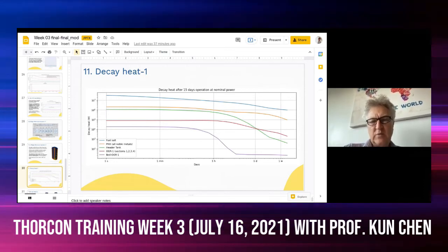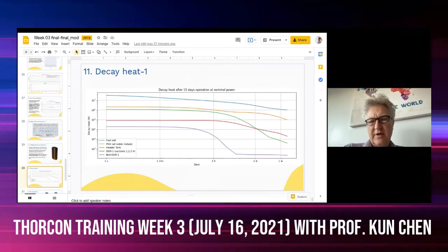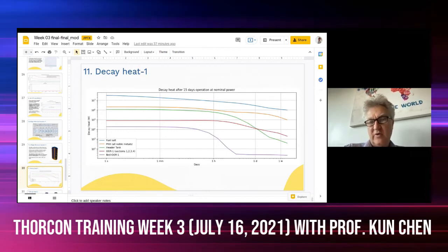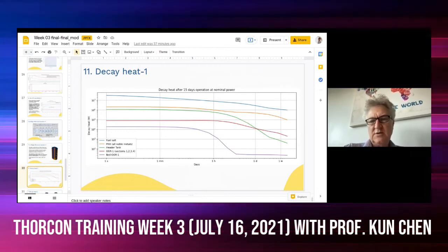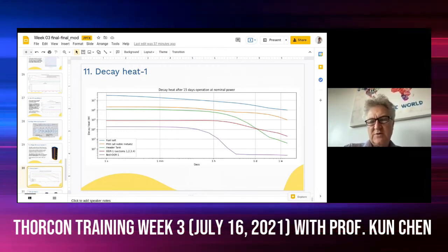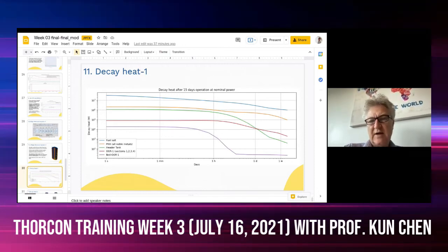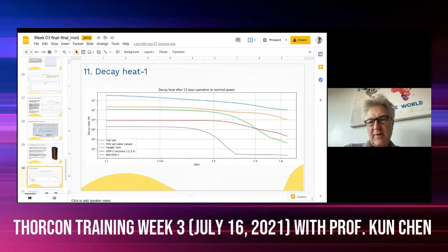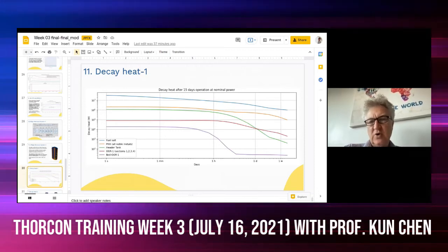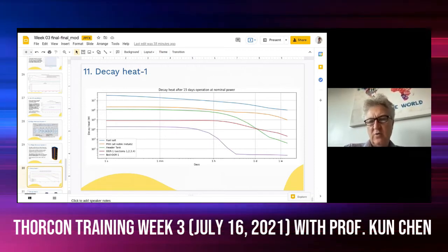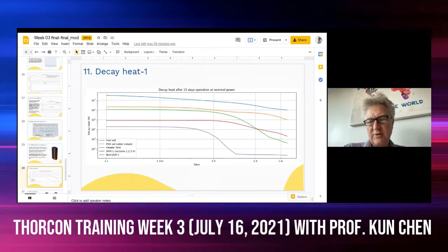However, as we pull less power out, the heat exchangers get to be more efficient. So when you reduce the power, you see the temperature rise as you go down the heat exchanger chain. The bypasses are used to reduce the temperature rise so that we hold the steam temperature constant.